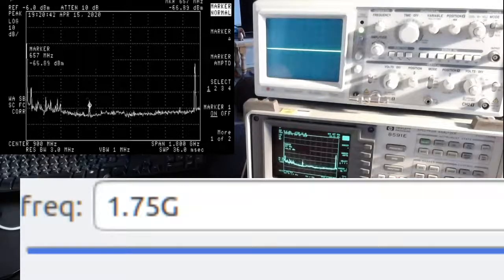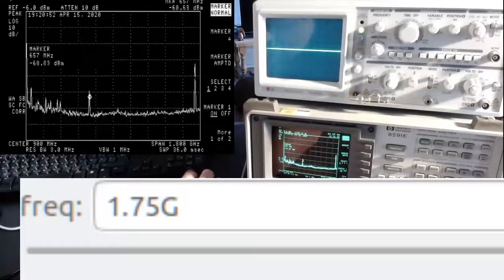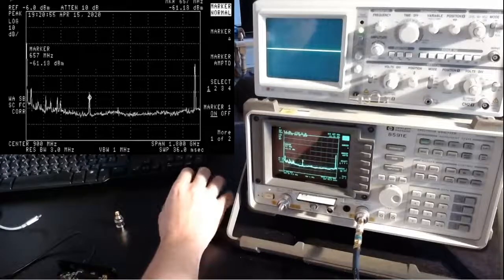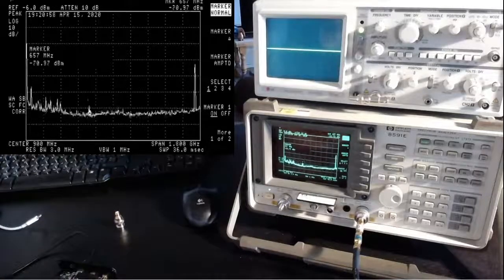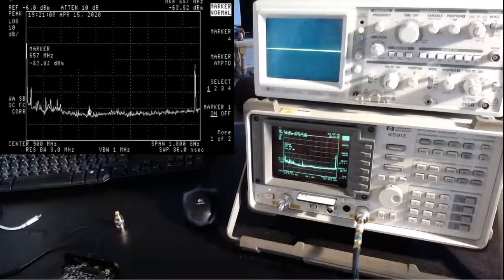So yeah, my conclusion after this first very rudimentary experiment, as just an application of my spectrum analyzer here, I can say that the HackRF definitely needs some filtering at its output if you want to transmit it with some significant power, so to send the output of the HackRF to an amplifier for long distance communications. This is, by the way, expected. This is in the documentation of the HackRF. They strongly recommend to apply some filtering at the output.